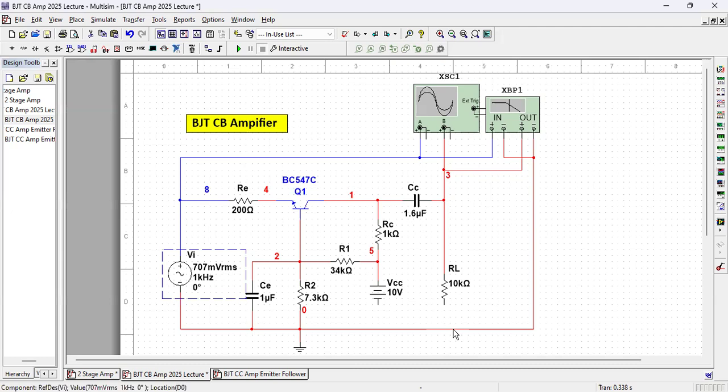A multimeter injects a DC current into the system, and within itself measures the voltage and current and shows you the resistance value. But if you supply DC, it will not work because there are so many decoupling and coupling capacitors. So you have to give an AC voltage and measure the AC voltage and current.